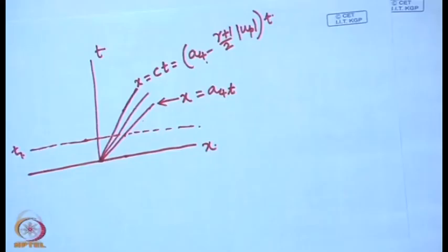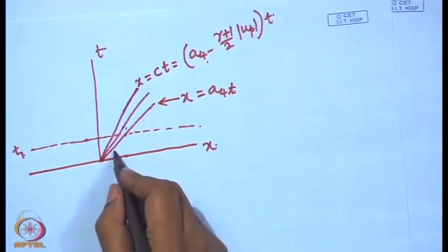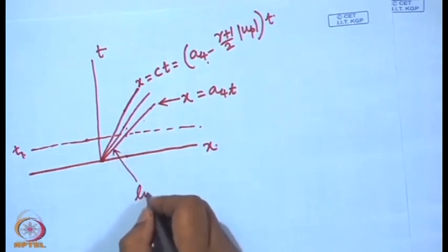Now, we see that the wave speed decreases continuously, since the absolute value of u_p is positive, of course, and it enters as minus u_p. So, the wave speed continuously decreases, as we can see from here. These fans of straight lines that we are showing here are lines of constant c and thus of constant u and rho. They are lines of constant wave speed,